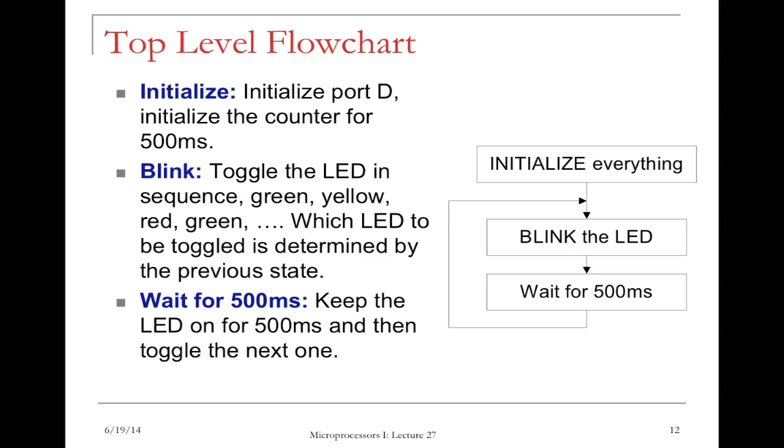So what do you have to do to turn this LED on? You want to output a high voltage, right? So like 5 volts on this end, across the LED, and this is the ground. And that's how you turn this LED on. Or of course, depending on how you connect the polarity of the LED, but normally you would output high to turn on this LED. And to output a high, what we want to do is actually we're going to tell the microcontroller that we're going to use port D as an output port. For each pin of the microcontroller, you can use it as an input port or an output port. You choose either way. But you have to choose that. You have to tell the microcontroller that we're going to use port D as an output port.